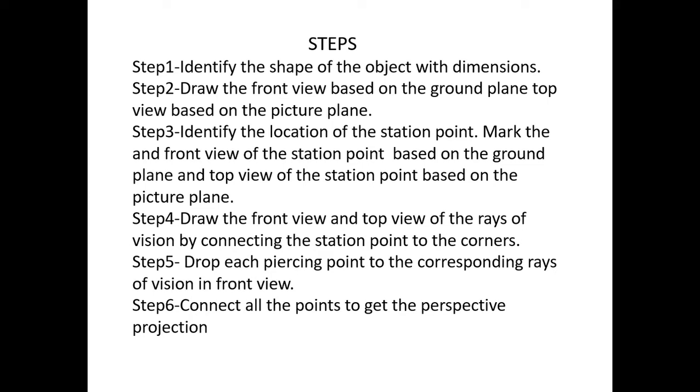Third step, identify the location of the station point. It is given that the station point is 120 mm in front of the picture plane and 80 mm above the ground plane. So you can mark the station point.